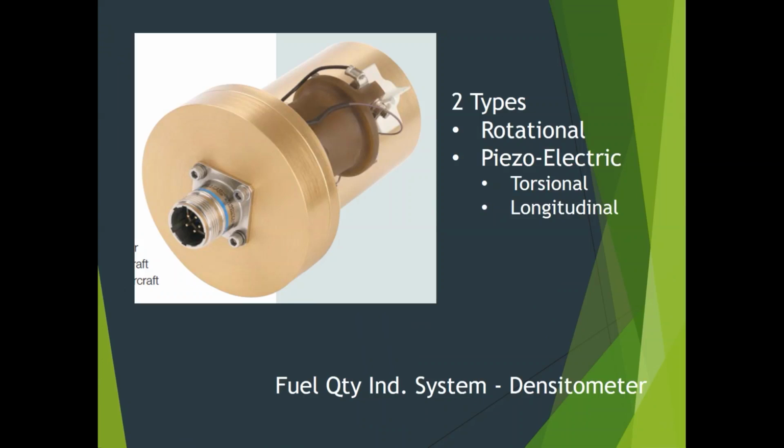A piezo crystal can also do it. I think what you're getting at is that if you apply a vibration to it, or a movement to it, or pressure, it will produce a current. So you put electricity to it, it's motion. You put motion hitting it, it gives a current. And so you actually have kind of an input, a piezoelectric crystal that's making this thing move torsionally, left, right. And then there's a second one hooked to it that motion is causing a current to feed back, a certain AC current to feed back. And we're looking at the frequency of that return current.